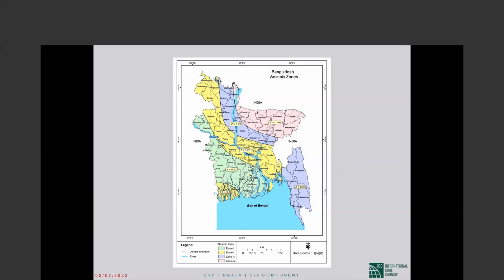Basically, you can increase the stiffness of the building by putting shear walls in wherever there is scope, or you can try to make those columns very ductile after the fact, which is a very expensive solution. And there are other innovative things you can do, but there are only expensive solutions. So the owner has to be willing to spend the money and engage the right help, and even then it is not going to be easy.